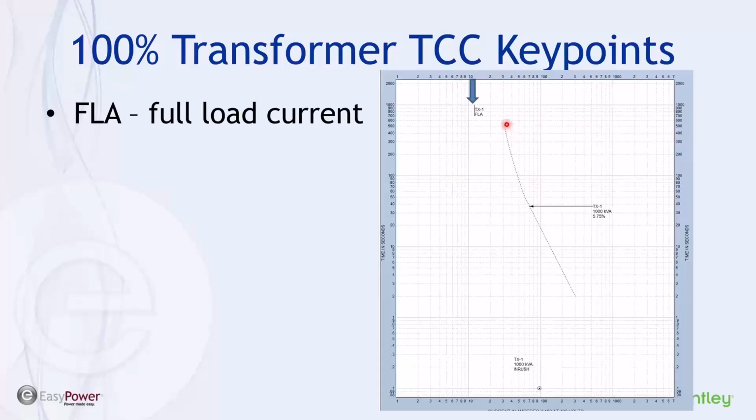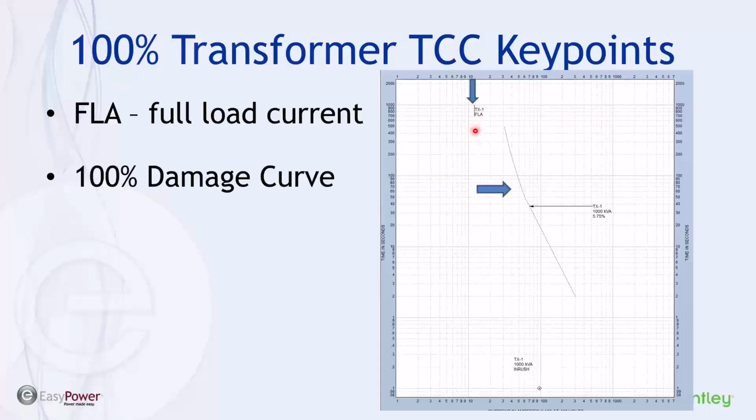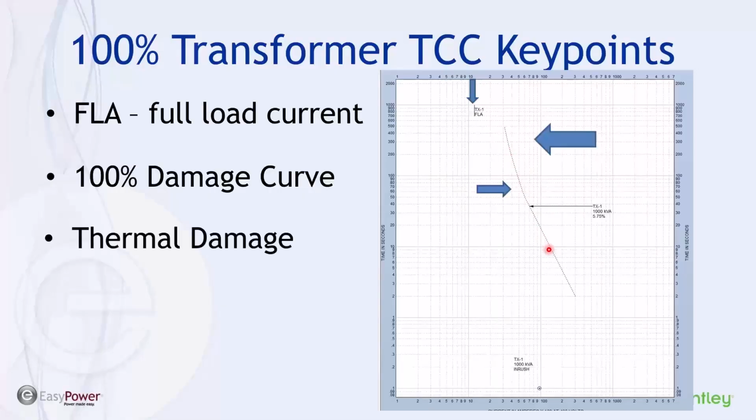So this is a result of the capacity and the voltage and impedance ratio, and so it's a fixed value. The 100% damage curve is therefore described by, as I say, the standard C57. The upper limit, which is the longer time exposure, although it's lower current.